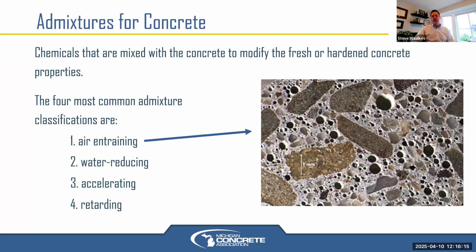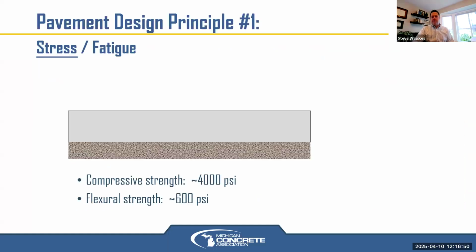There's definitely a factor of safety for the design, and then also in the specification and the mix design to achieve that specification. So there's typically factors of safety involved. If you do get high air, it's generally not a main concern. Once it gets much higher than 10%, you start seeing permeability issues, which then could potentially lead to some freeze thaw issues. But yes, you could potentially have too much air. Most specifications obviously limit that, but high air is generally better than low air when it comes to durability, and that's the main reason we put it in. So good question.